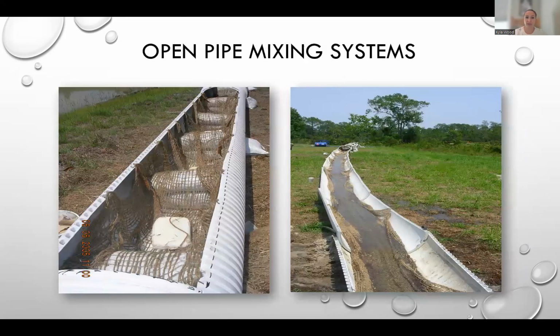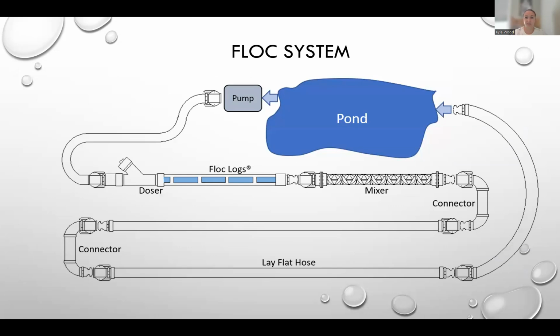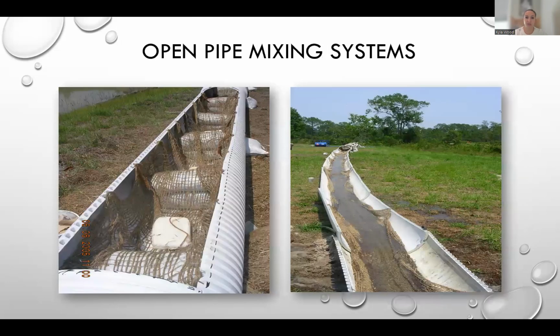These can be done in a lot of different configurations. They always consist of a pump, some way to dose the system, and then enough mixing and reaction time, which might look like 100 to a couple hundred feet of hose to finish forming those flocks before you discharge.